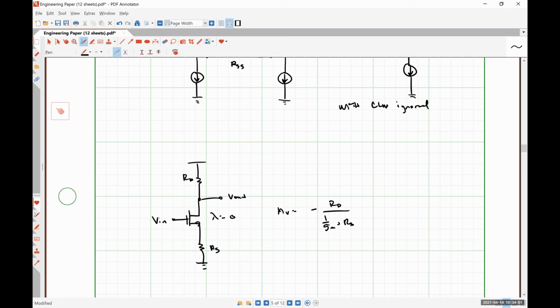All of these differential pairs are based on roughly common emitters with or without degeneration, so it might be good to write those two basic guys down. But you shouldn't see anything that is common base or emitter follower or common gate or source follower on here.